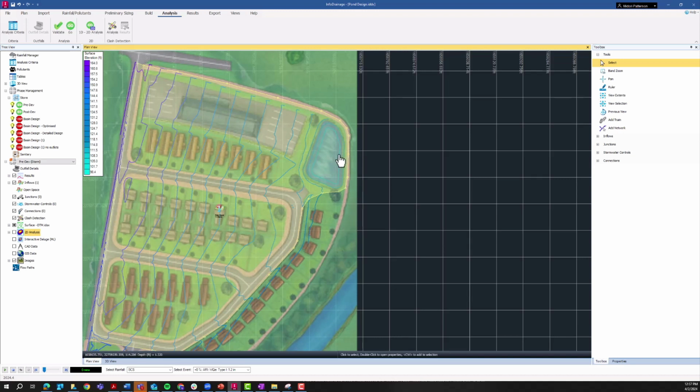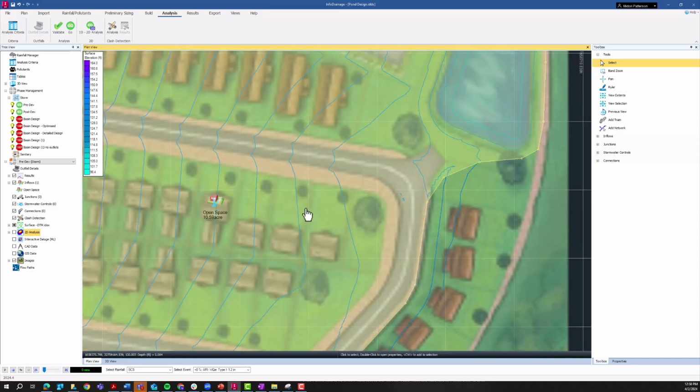So once this is filled up and you start to discharge to your downstream water course, the rate of that discharge is also something that is typically regulated. And a common thing that stormwater authorities will check is that the runoff rate of your new developed site does not increase from the runoff rate that was on your undeveloped site.